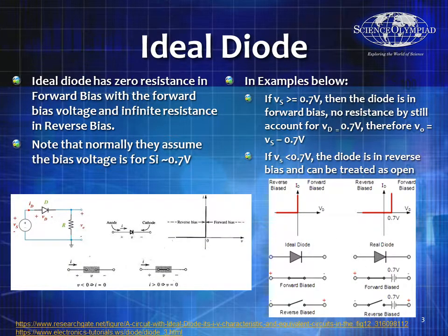We talked about ways to draw the current versus voltage curves for an ideal diode, and then how to approximate a real diode by putting in a forward bias resistance, which is usually going to be very, very small. Keep in mind, most of the problems are for a silicon diode. So if you are going to put in the forward bias voltage, it'll be 0.7 volts.